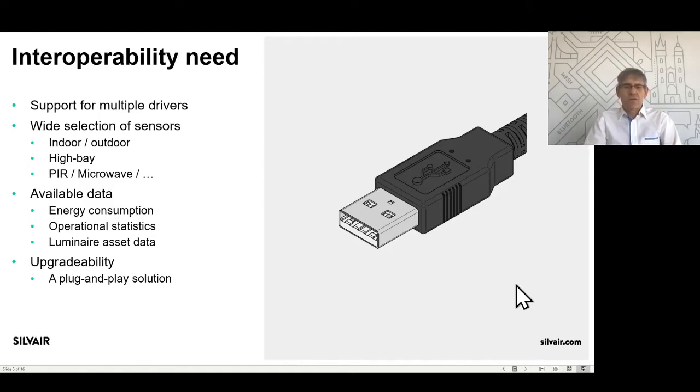They are all gone. USB unified all of those into a single form factor, which defines the physical type of plugs. It defines the electrical interface, the wires, including how the power is delivered over USB, as well as the application behaviors. So you plug in a USB thumb drive and the system knows that this is a storage device.